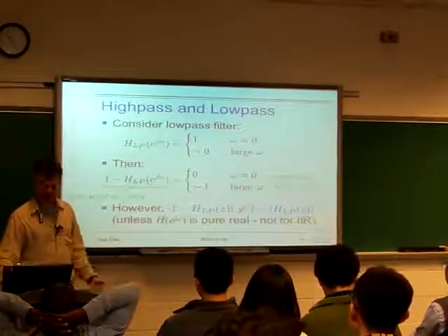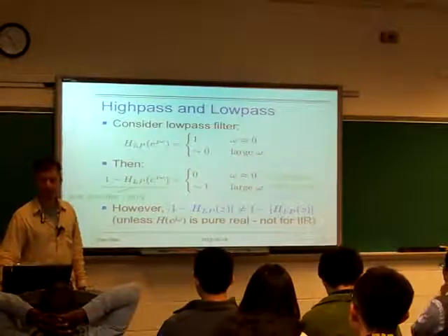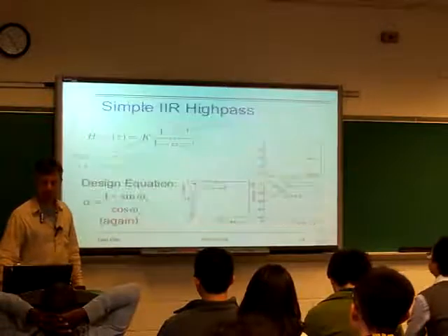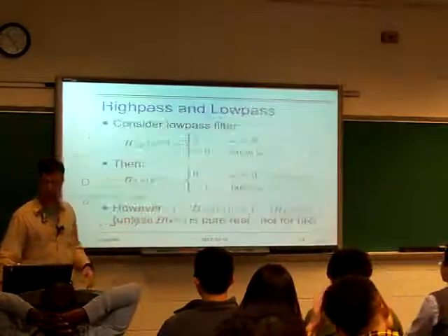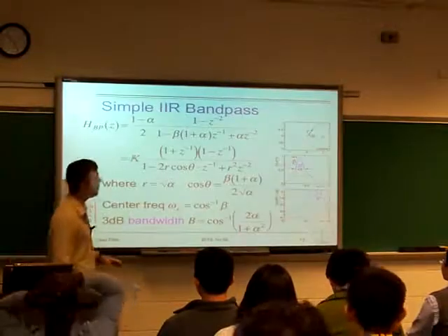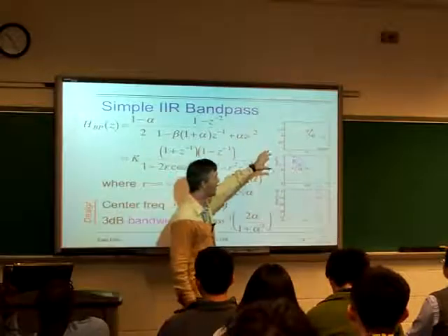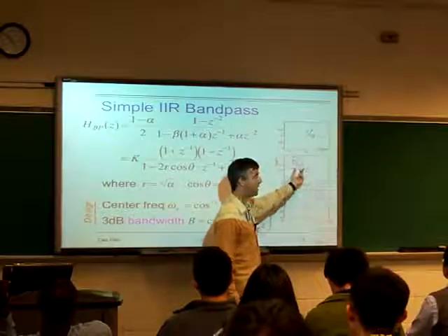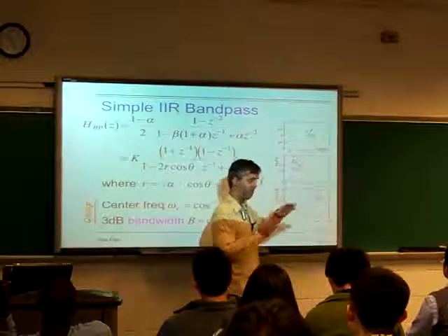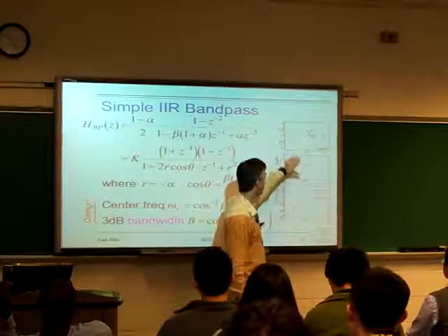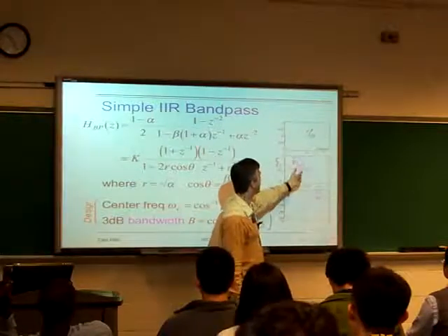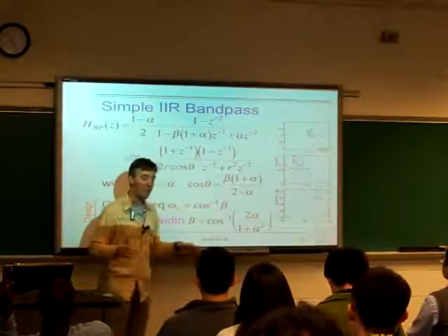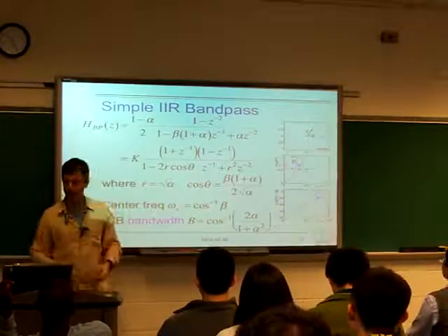And then there are different classes of filters for different things we want to do. The high pass and low pass are kind of simplistic, but once we get onto band pass filters, even with just two poles, this is already a useful filter. You can pick out a range of frequencies, you can vary the width of that range, and you can correspondingly vary the amount by which it selects a particular frequency, the gain at that frequency compared to its neighbors.